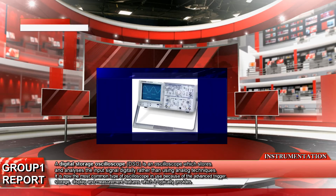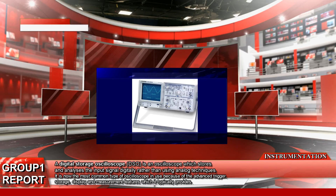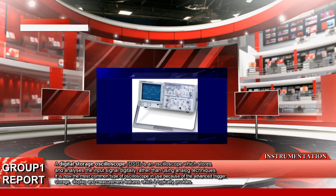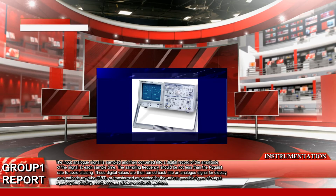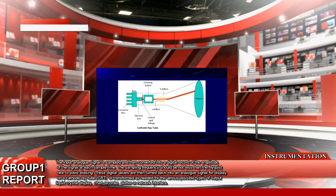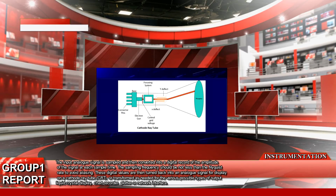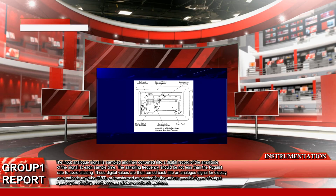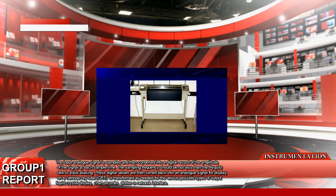The input analog signal is sampled and then converted into a digital record of the amplitude of the signal at each sample time. These digital values are then turned back into an analog signal for display on a cathode ray tube, or transformed as needed for the various possible types of output: liquid crystal display, or LCD, chart recorder, plotter, or a network interface.